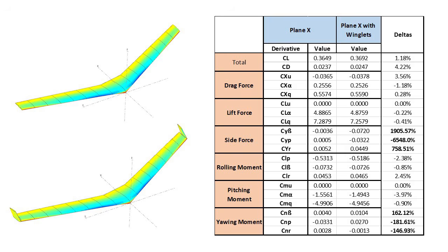I'm a bit suspicious about the change here. If I was to go back and make a third iteration of this, I think I would focus on understanding what happened here. CNR is nearly 0 and flips to negative with the addition of winglets. And like we just saw, the roll yaw coupling enhancement can cost the yaw damping and then flip the sign from near 0 positive to near 0 negative.